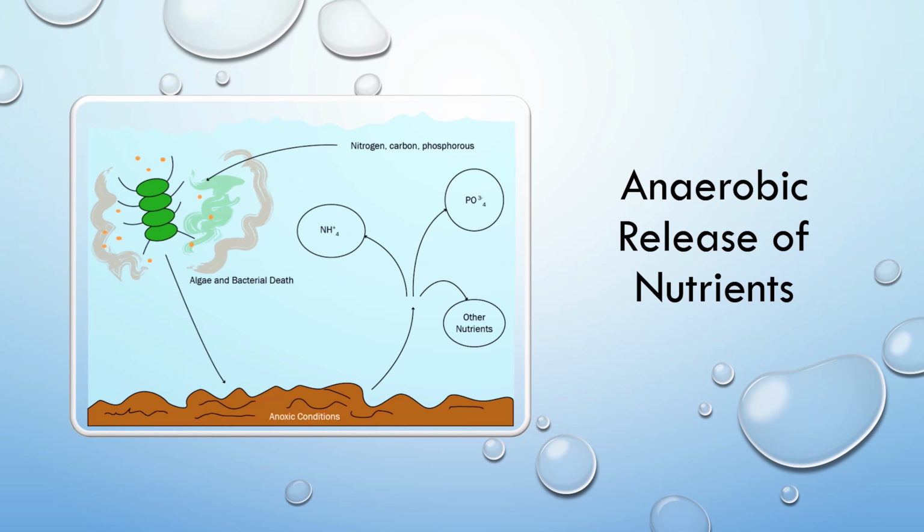The soluble ammonium and phosphate are used by organisms in the water column, mostly algae, to grow. This may lead to a bloom of algae, sometimes bacteria if you also have high amounts of soluble organic carbon in the water. And these planktonic organisms will lead to higher effluent TSS and possibly higher effluent BOD or ammonia. After some time, the algae and bacteria will die, and their cells sink to the bottom again and contribute to this buildup of sludge and further the anoxic or anaerobic conditions, leading to release. So this cycle will continue.